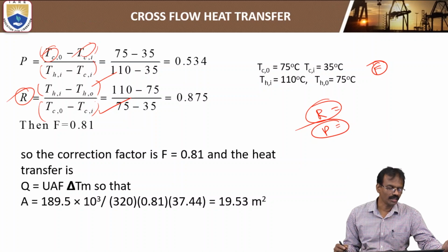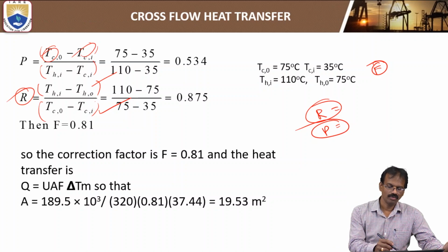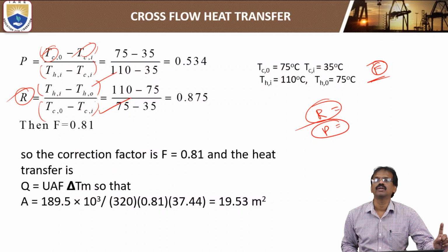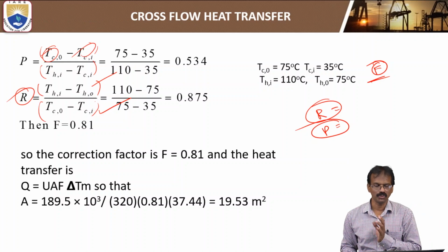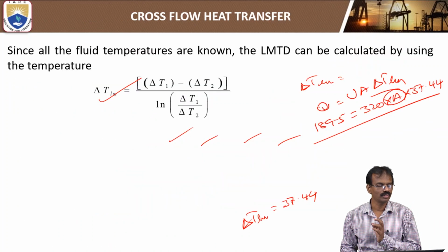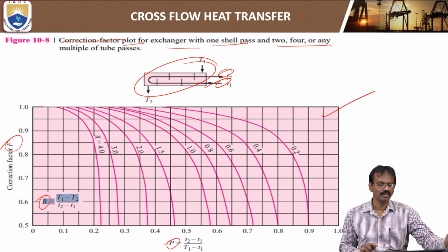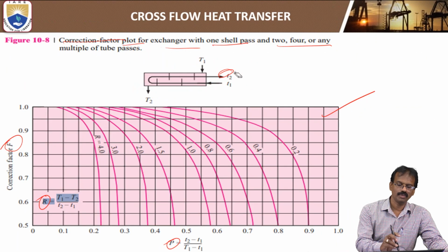By using this R and P, you find out the F value from the figure related to one shell and multiple tubes.